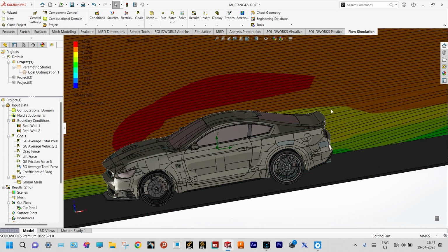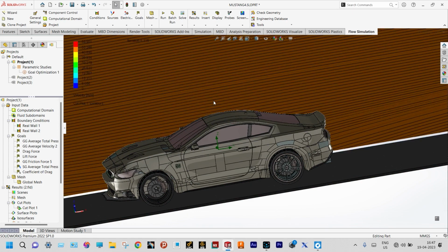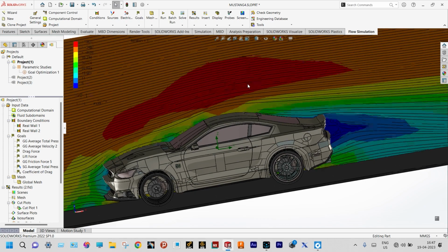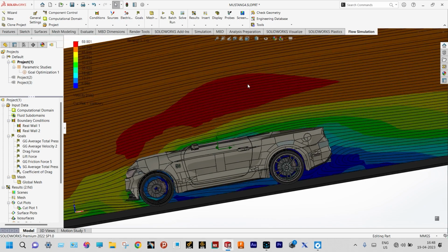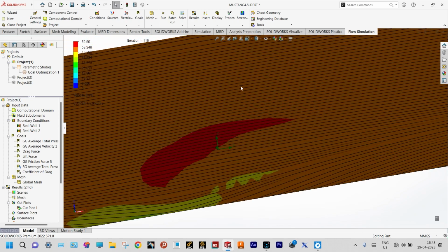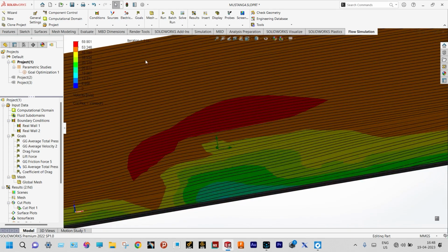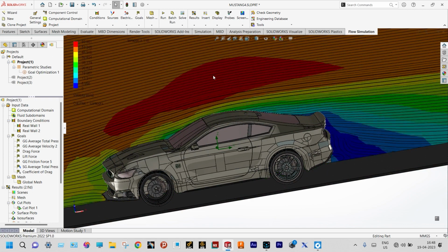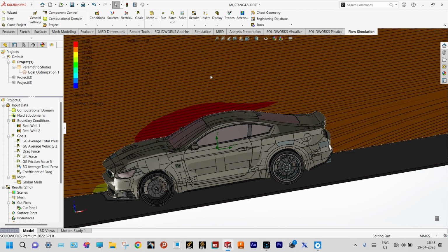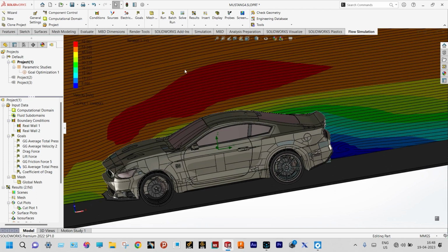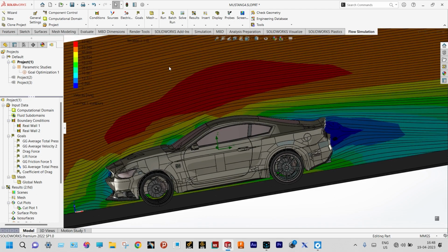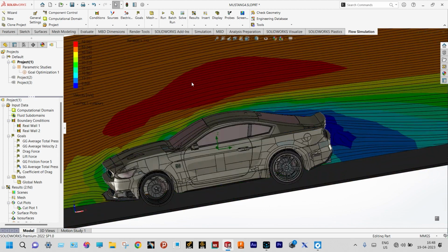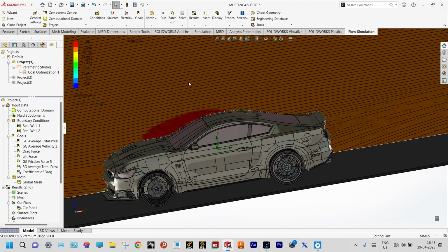And also the velocity at the top surface is more. There is a reason for it, because we have reduced the computational domain. If we could have maintained the computational domain with a high value, then definitely you could have seen different results at the top surface, right? Because if the volume is confined to a specific zone, according to Bernoulli's principle these things may happen at the top surface. To have better results, we could have increased the height of this computational domain,